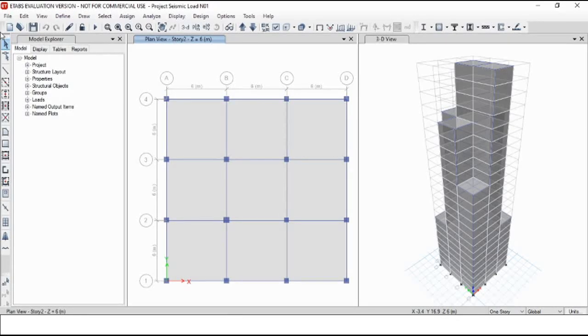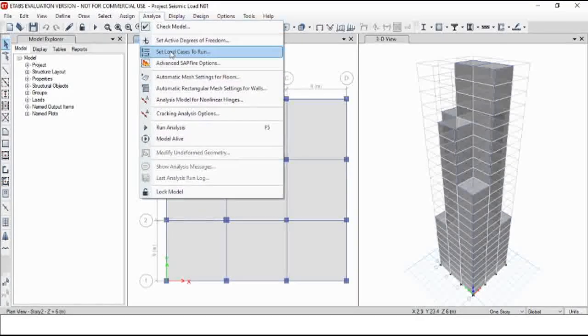Now up next we'd be going for the analysis and design of the structure. Now in response spectrum method, we need not individually select any members of the building, as in the case of dead load, live load and wind load. Various shells and members were selected, but in this case entire building is under consideration in response spectrum.